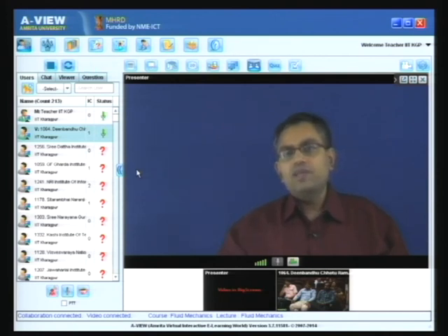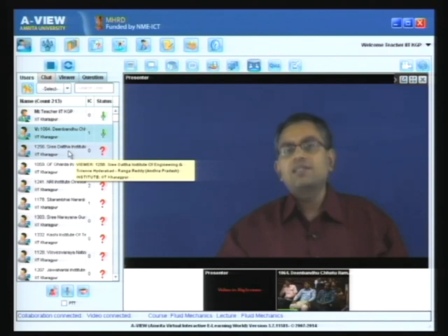If these body couples are there, then tau ij is equal to tau ji plus some correction term which is a function of the body couple. If the body couple is not there, then tau ji and tau ij are the same.